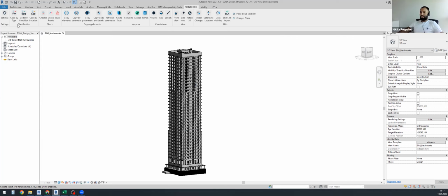These features are divided into different groups. So for example, a group for classification. In this section, you can work with the design BIM model and classify elements based on classification code, assembly code. The next section of features is checker. So you can check element properties and upload check results that are done inside SIGNAX tools for Navisworks. And we have support for BCF files.